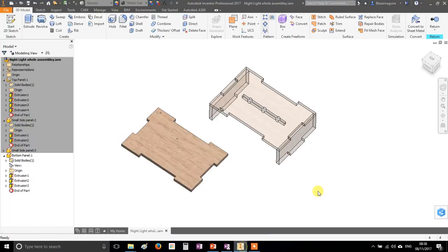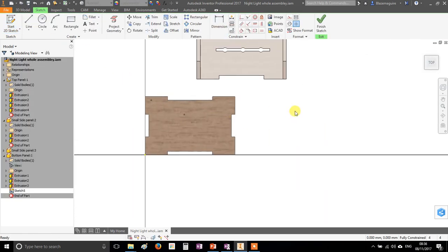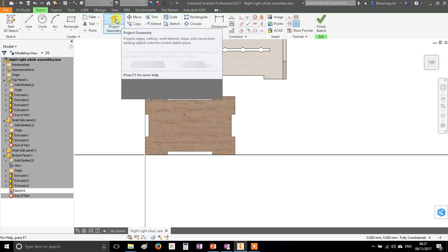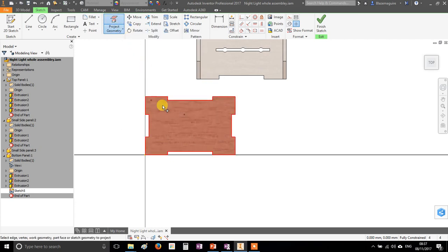Really easy to do. Make a new sketch, because we're making a feature, so sketch on the surface here, and you are going to use a new tool now called Project Geometry. Project Geometry, if you just move so the whole thing's highlighted and click, you'll see it draws this yellow line around everything. Your next tool, you're going to use Offset. Offset does what the picture looks like.